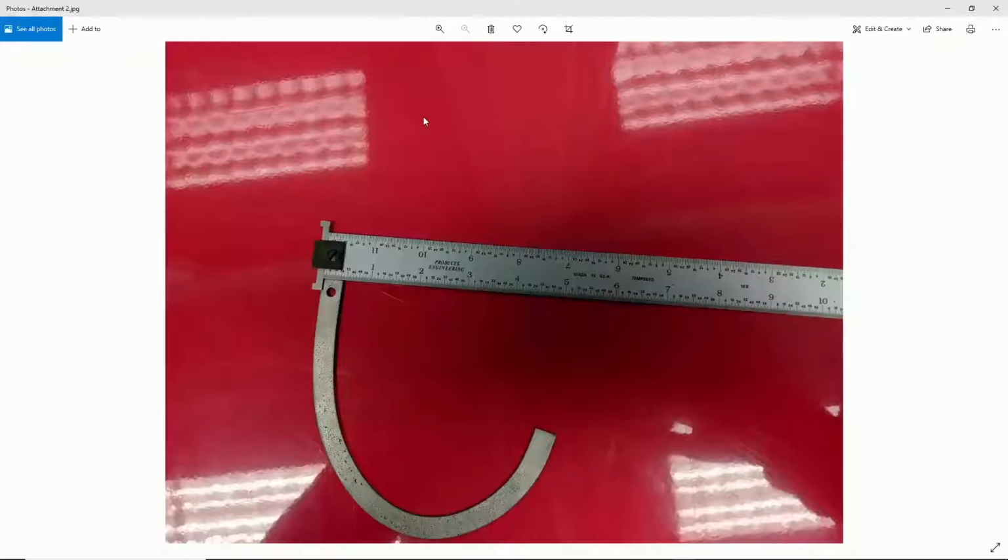So what we had him do is mail me the gasket, and then I got a piece of, I think it was quarter inch divided square graph paper, and I just traced it with a real fine tipped pen and plugged it in, and then we were able to use that geometry. I brought it in, drew everything out, cleaned everything up, and then we cut a stamp. We basically used a V-bit and had it come to a point.